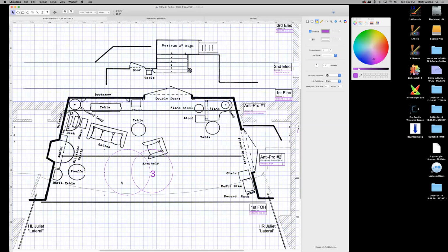So I draw my circle, and it immediately turns my cursor into the pointer, and I can move this around. Now it's ready to reposition where I want it to. So for area 1, I would drop it over here and say that's area 1. Now, once you've created your first circle, the simple thing to do is to highlight it and click copy and paste.